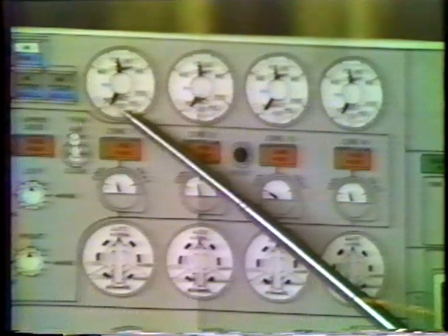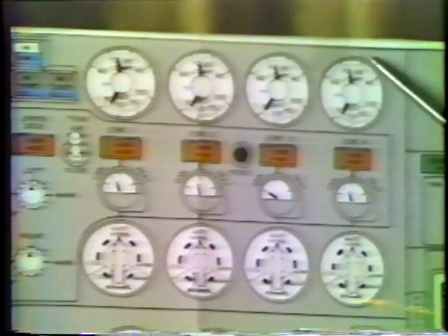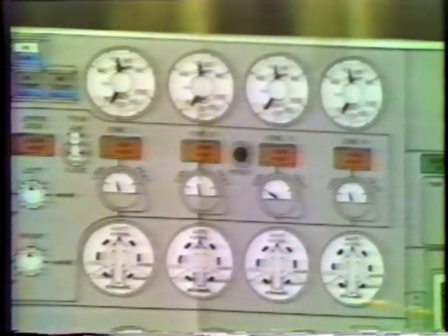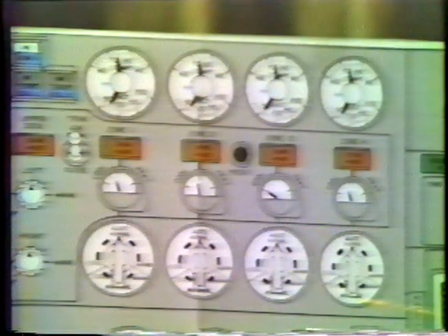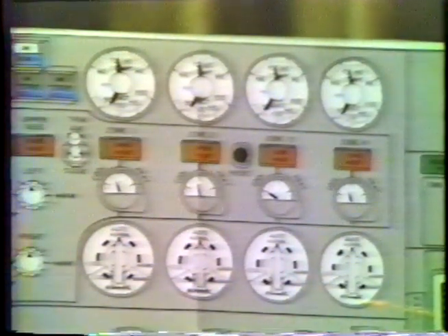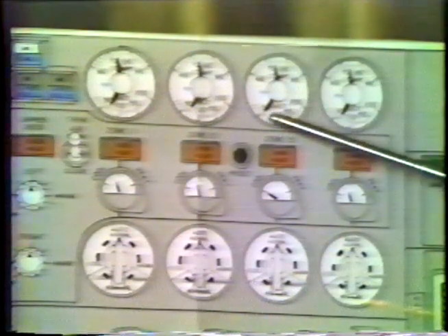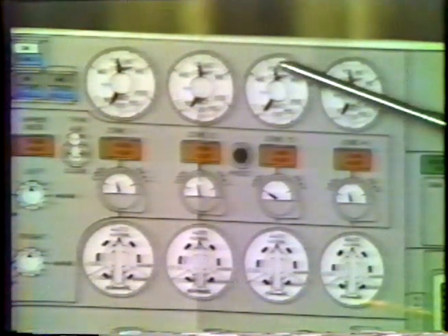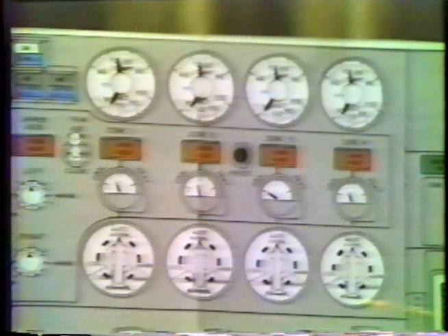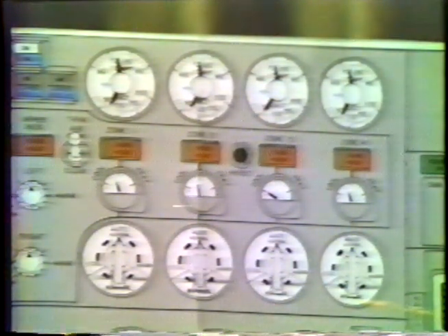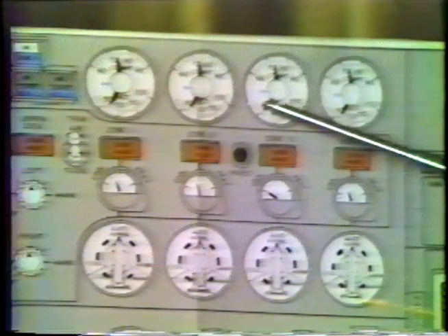The gauges above indicate the duct supply temperature and the compartment temperature. And of course you would expect the difference between the two to depend on what you're trying to do to the aircraft. For example, if we're on the ground and it's a hot day, you would expect the supply duct temperature to be somewhat cooler than the actual cabin temperature when we're trying to bring the cabin temperature down. However, if we're at cruise and it's very cold outside, then the duct supply temperature would be hotter than the cabin and we're trying to heat the cabin.